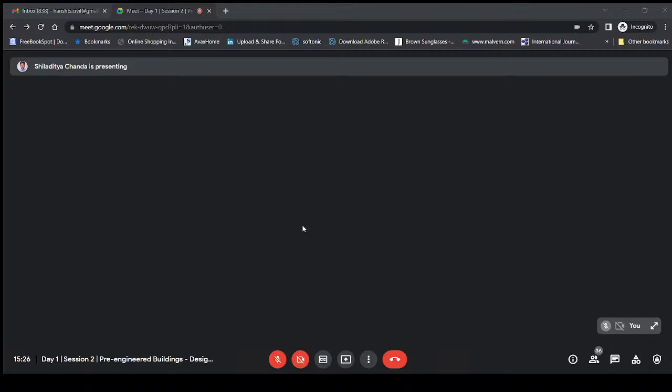And a little bit about STAAD modeling. Most of you are very conversant with STAAD, and some of you are more conversant than me. So as you know, in STAAD, when you detail this, you have to input the tapered property for a tapered section. One part is deeper, another part is smaller. So here, the depth of the section at the start node should always be higher. This is a limitation in STAAD, and you should follow that.